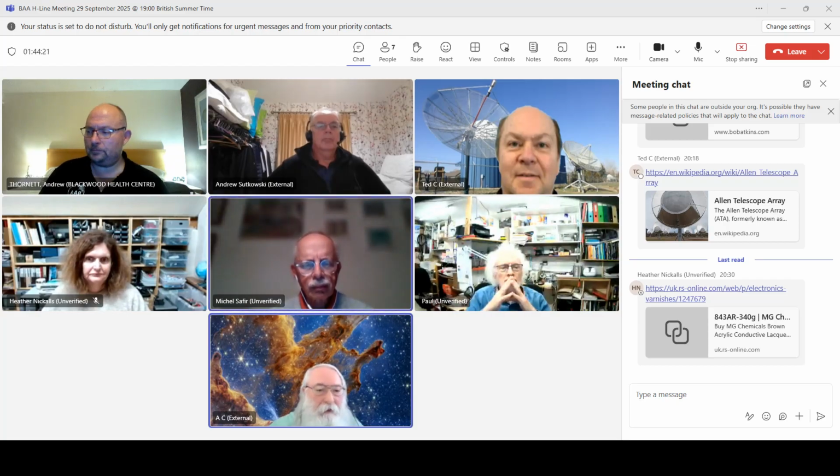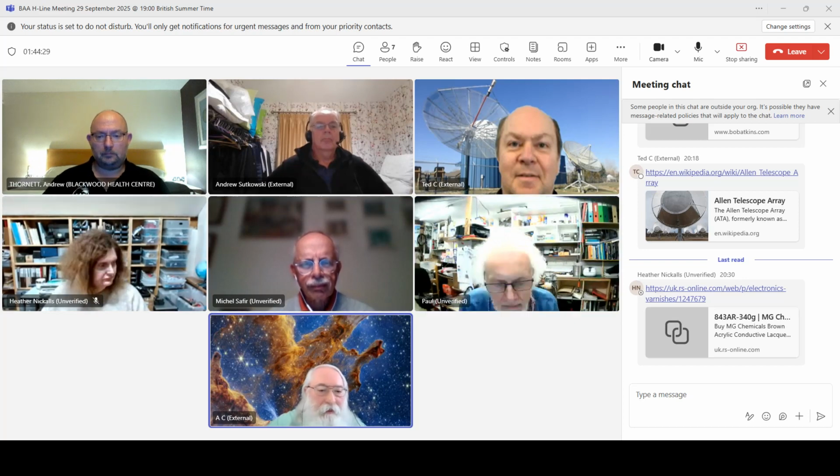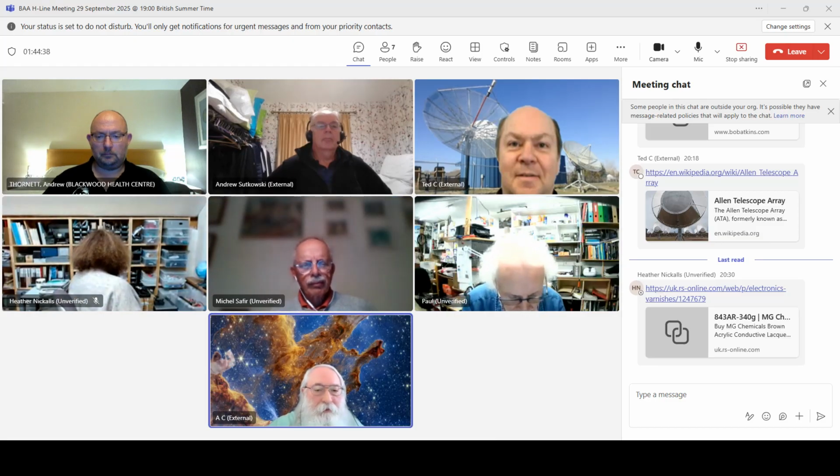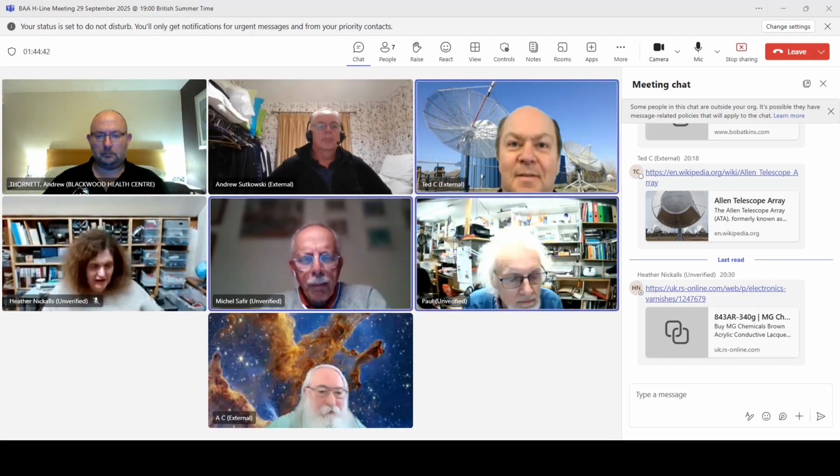It's sort of like a regular antenna. If you want to make a dipole, you have to use the quarter wavelength rule. So you can't just arbitrarily change the size and have it be resonant at the frequency that you intend to be utilizing it for. So yeah, those dimensions would have to be adhered to. Thank you.